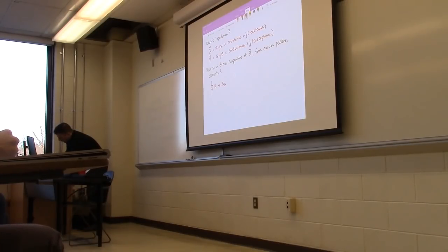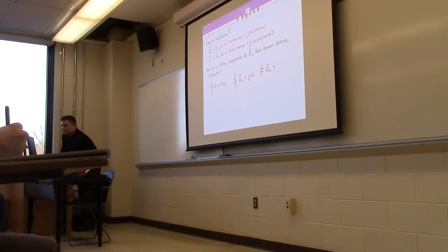Okay, you have your inductor, and so that has a value, we'll call it ZL, so that'll be the inductive component of the impedance, and so that's equal to J omega L. And then we have the capacitive element. And anybody remember what that's equal to? 1 over J omega C. Yeah, 1 over J omega C, which is the same as negative J over omega C.